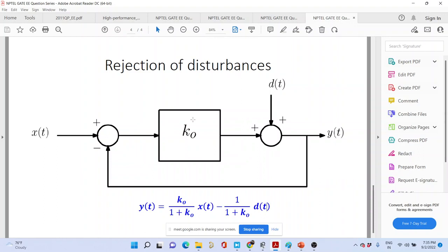So if you increase the gain, the disturbance gain factor would become equal to unity, and the disturbance will stay in the output. You will not be able to reject that disturbance. That is a bit of a difficult thing to do, and you would read it in postgraduate studies. But the main key takeaway from the questions that I've asked is, the mool mantra for designing any control system is to achieve high gain.